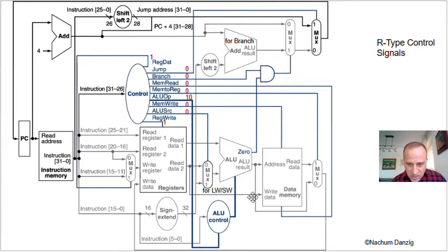It also goes down here and straight into this multiplexer. Well, that's the value that we want. Remember, this is an add. So essentially we did 7 plus 5, and we want to have a 12. And we don't want the 12 to go into memory. We want 12 to be our number that we're going to put into the RD. So it's sitting here on this multiplexer.